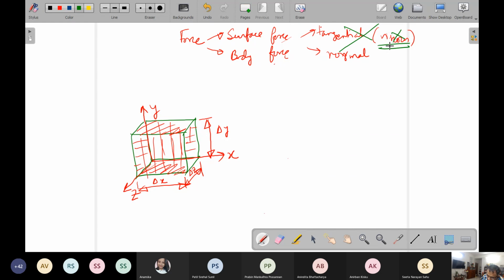So in that way, for inviscid flow, we can safely say that the normal force that we are talking about here is due to the pressure distribution. Now pressure, we know by its physical nature, always acts normal to a surface and inward normal to a surface. That means it is like this and this, this and this, and maybe from the back and in the front. So from the pressure, it is quite clear that it is trying to compress the material.